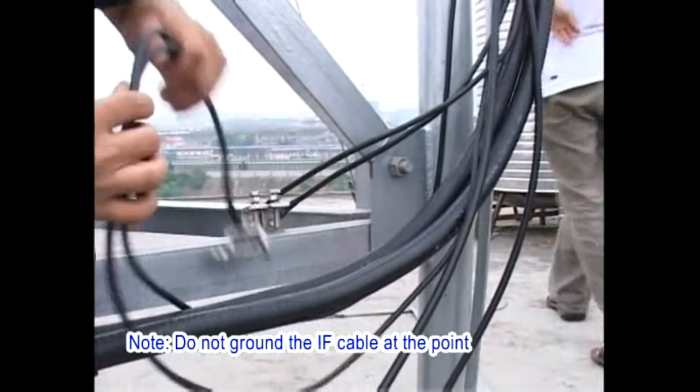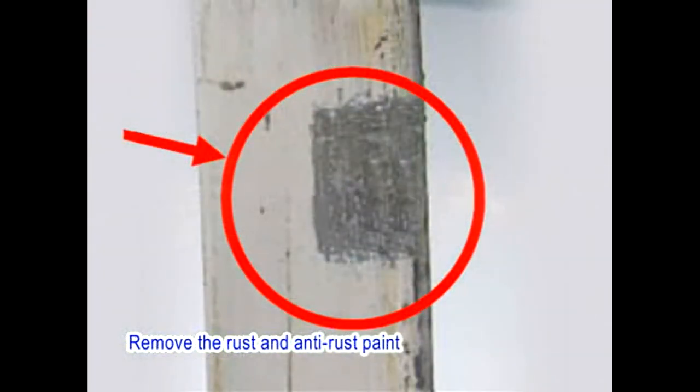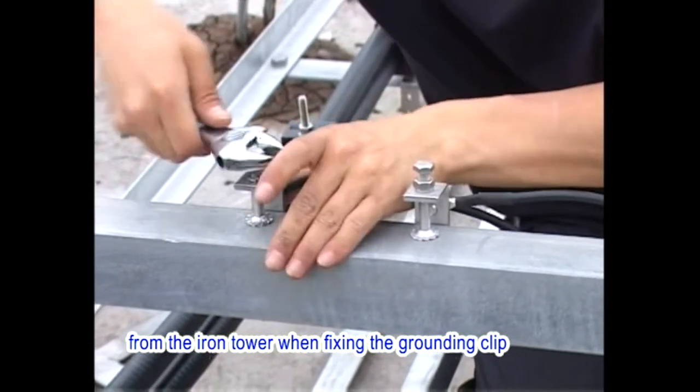Note: do not ground the IF cable at the point where the cable is bent. Remove the rust and anti-rust paint from the iron tower when fixing and grounding the clip.